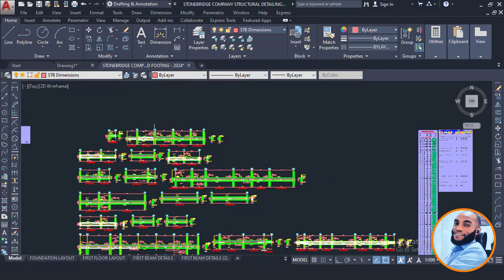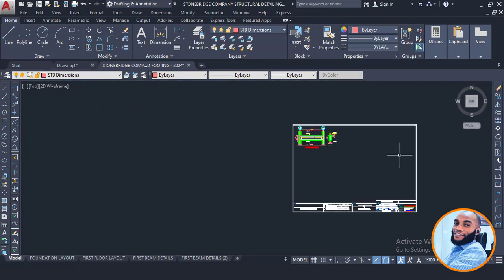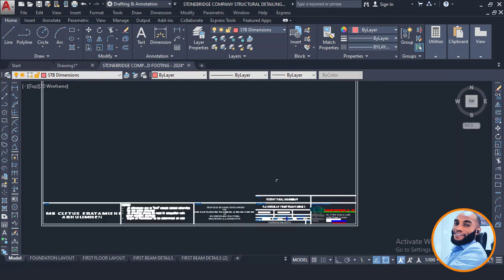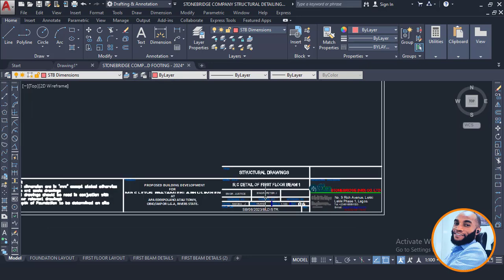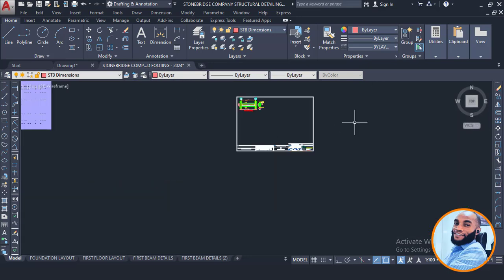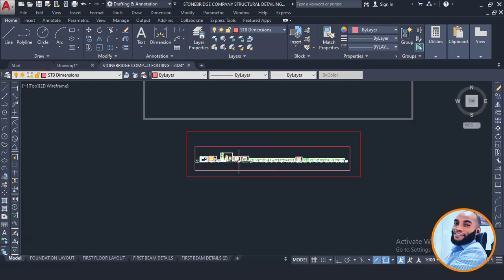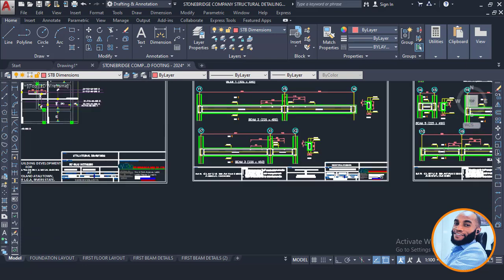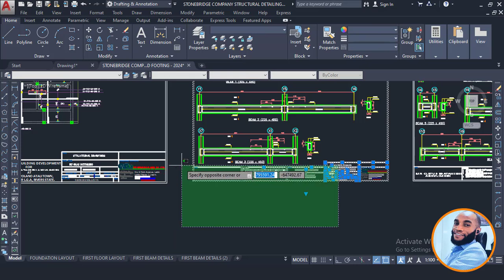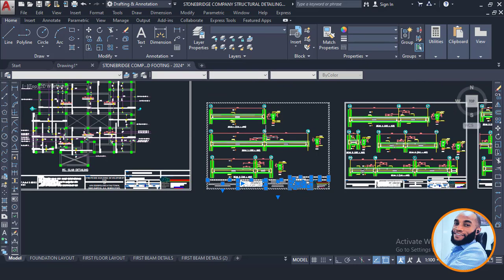But if you are copying your own company title sheet into this place here, I advise, sorry, I didn't copy this very well because there's a small mismatch here, so I'll quickly take this off and go back here and copy the particular size for beams. So if you are copying your own company template into this place, make sure you scale it to the exact size for these beams so that your drawings can be printed perfectly and accurately, to scale.